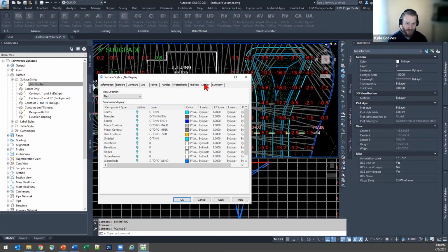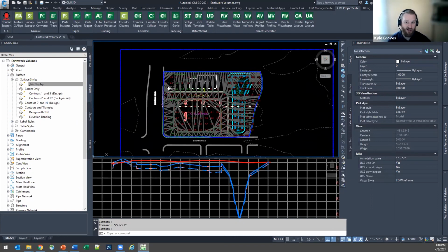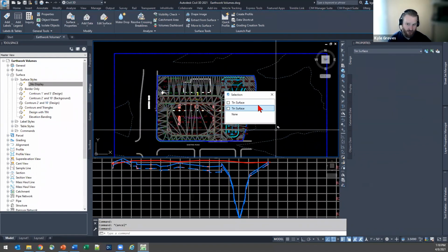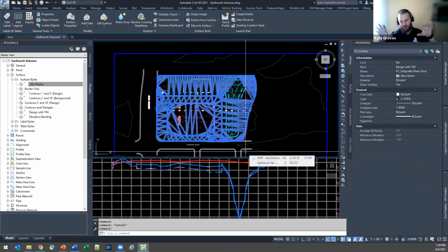It is just your display tab. For most of your objects, alignments have some markers that you need to care about, but you go to your display tab, you go through all of your view directions, and you just turn off all of the light bulbs. With that set to no display, you're going to have your drawings running way lighter weight, and it's also a lot more convenient, in my opinion, than freezing the layer of the source object, because Civil 3D styles and AutoCAD layers have a lot of strange interactions. Strongly suggest your Civil 3D stuff, you don't want it, you turn it to a no display style. It's the easiest way to keep track of all of that data.